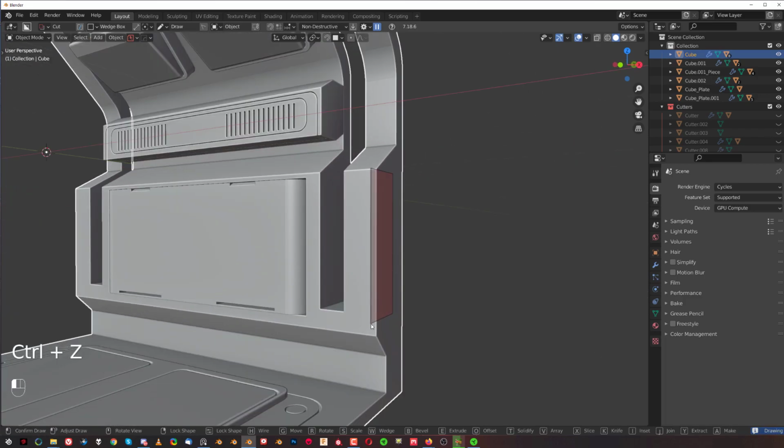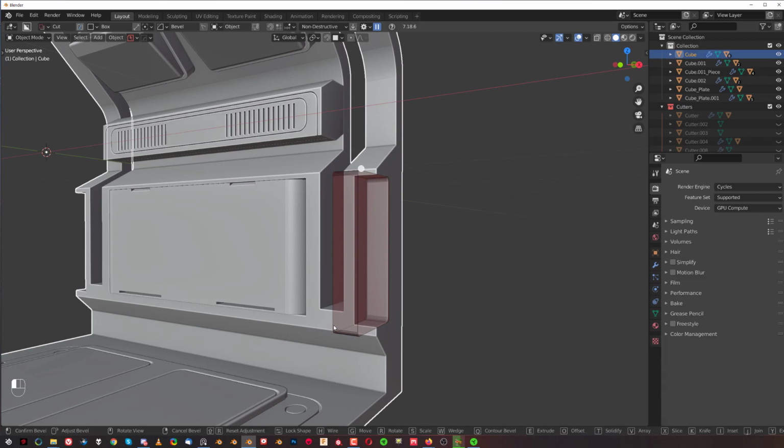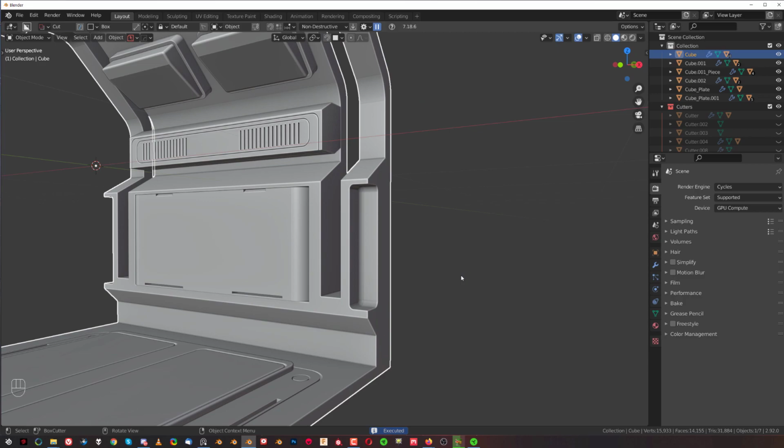I'm going to do something else in here. I'm going to create a cut here, like that. Regular cut, but I'm going to bevel this from this side and press Q for quad bevel. So I'm going to bevel it from all sides. Okay, so something like this.